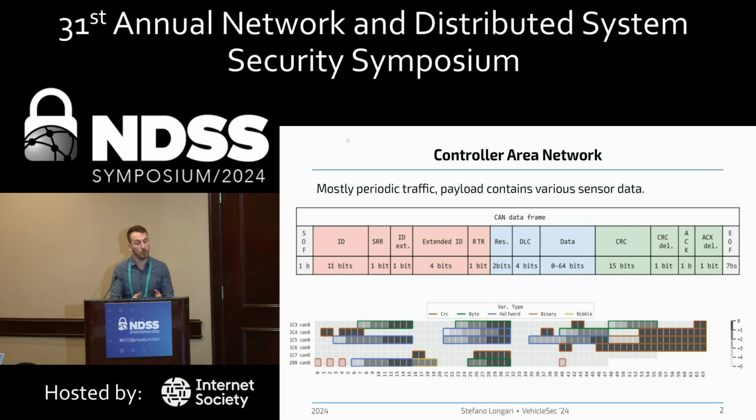Thank you, sorry. So we were talking about evasion attacks against intrusion detection systems, and specifically we're going to focus on intrusion detection systems on CAN. I don't want to bother anyone with the whole story about CAN. We all know what it is. My main point is that, being an onboard network, it has two characteristics that I care about. The first is that packets are usually periodic, and the second is that the payload of CAN messages is often composed of sensor data, so sensor signals, right?